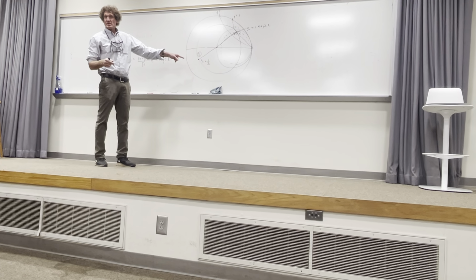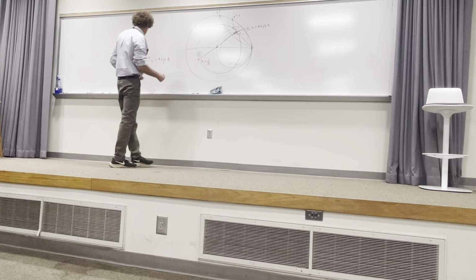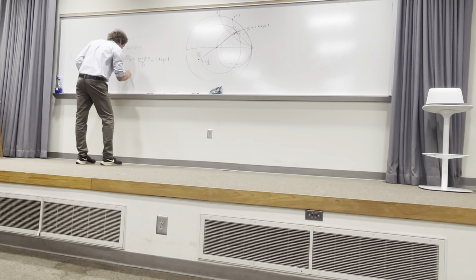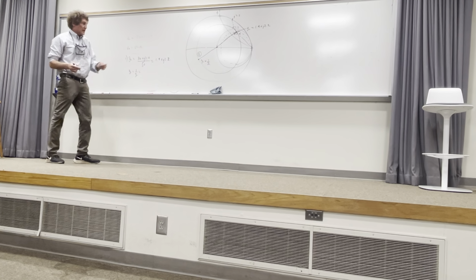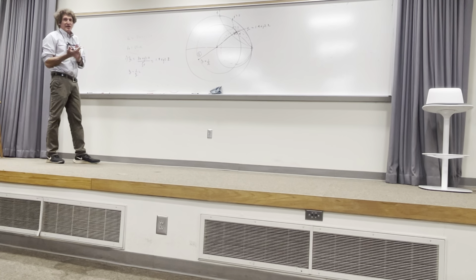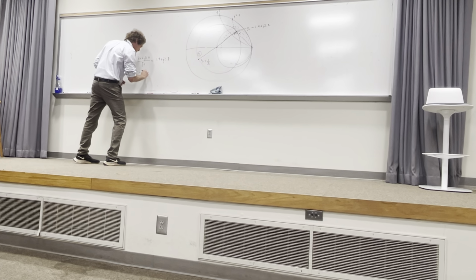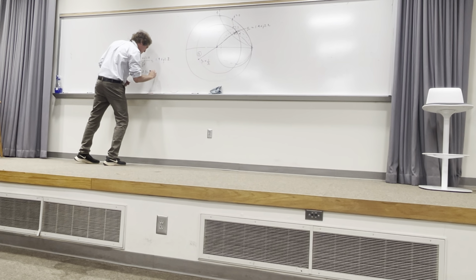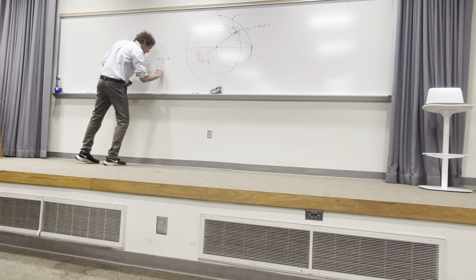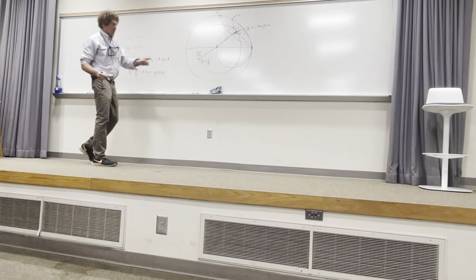You all with me on this, class? Now, YL is 1 over ZL, and I'm not sure what it is, but you might as well just tell me right here. What is YL? 1 over ZL. You can either look at it or you can use your calculator. Calculator is easier. 0.206 minus j0.324. That's fine. It's here, right?